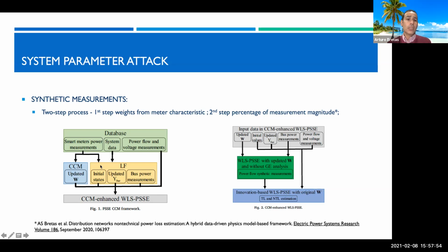And those power flow measurements, since the weights that you used are linearly independent, create a linearly independent solution compared with the weights that you use on the second step, which are based on a percentage of the magnitude value. Then this additive information is actually useful information. It's not redundant information. So those solutions will create additive information in your system that we call synthetic measurements. And those would be power flow measurements that we would then use as synthetic measurements towards analytics.